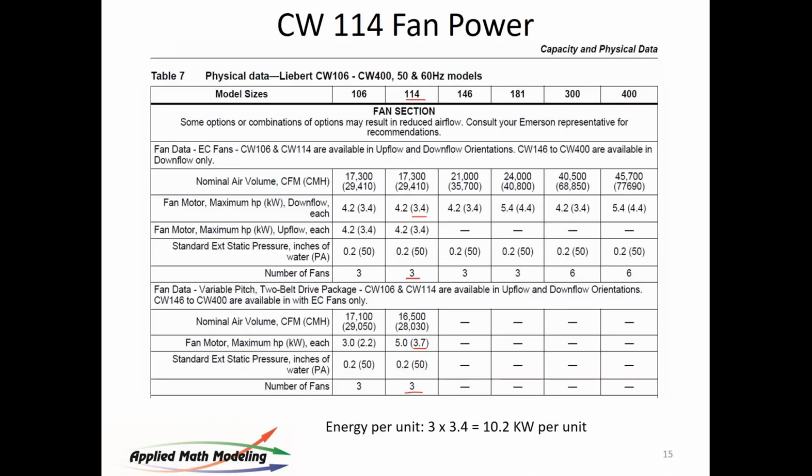Now on the energy side, I want to take into account this fan energy in the CoolSim model. So I pulled up the fan power section of the CW114 specification to show you how to do that. So here is the CW114. You get this from the Liebert site. They'll always list their fan motors. You need to choose the right one. There are two. This is the older style here with belts. This is the EC fans up here. And so it's important to know which one you're using.